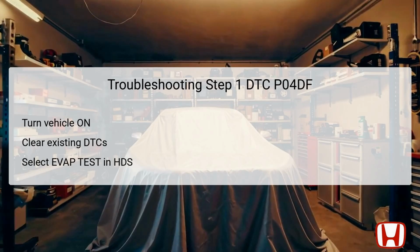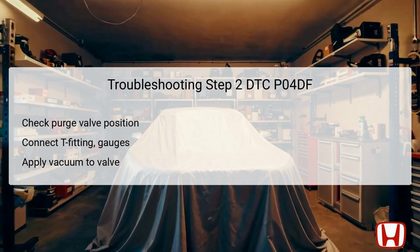Once in the on mode, use the Honda Diagnostic System, HDS, to clear any existing Diagnostic Trouble Codes, DTCs, from the vehicle's memory. This ensures that the diagnostic process begins with a clean slate by removing any potentially irrelevant codes. Following the clearance, select the EVAP test from the inspection menu on the HDS and proceed to run the function test. This systematic approach not only helps to isolate the current issue, but also provides insight into whether the problem is intermittent or persistent. Step 2 focuses on evaluating the condition of the